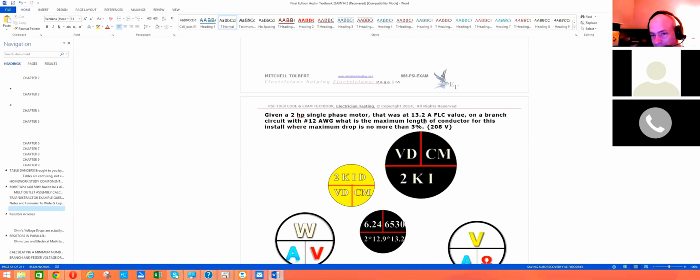Now, I suppose you could probably take that 2 out. No, you'd have to double that double. You'd have to do it 4 times. Okay. Anyway, regardless of one way or the other, that distance there is going to be the physical separation. And sometimes they'll ask you for the distance, and sometimes they'll ask you, like in this case, what that length of conductor is. And if they ask you for the length of conductor, you got to be real careful to make that little switch between the two in your mind and make sure that you're answering the right value. The Colorado Masters voltage drop questions were always asking for the length of conductor, and sometimes they would ask for the distance. So you kind of had to pay attention to which one they were really ultimately asking you for.